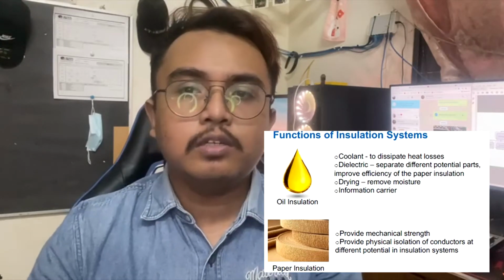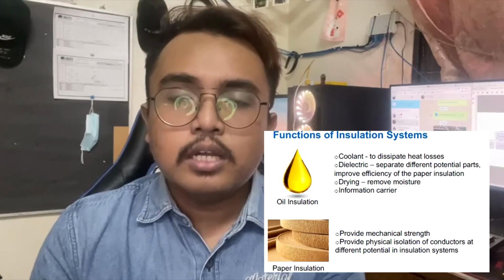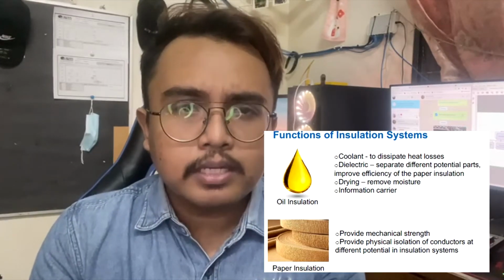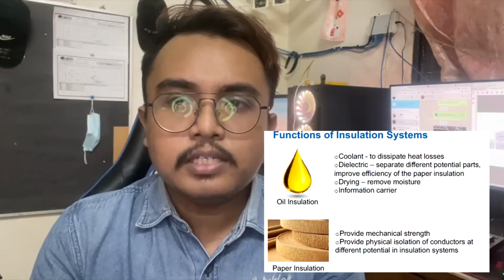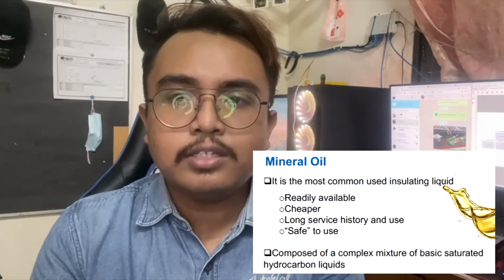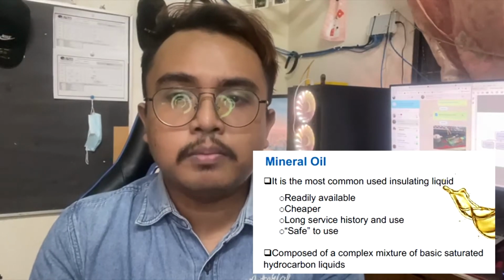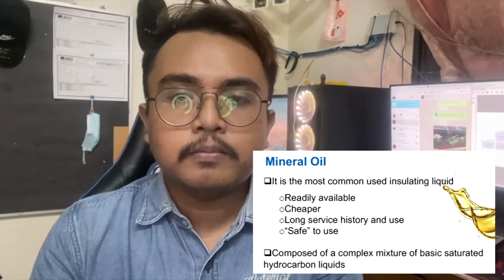The oil insulation acts as a coolant, dielectric, drying and information center. The paper insulation provides mechanical strength and provides physical isolation of conductors at different potential in the insulation system. Mineral oil is the most commonly used insulating liquid. It is used because it is readily available, cheaper, has a long service history, and is safe to use.